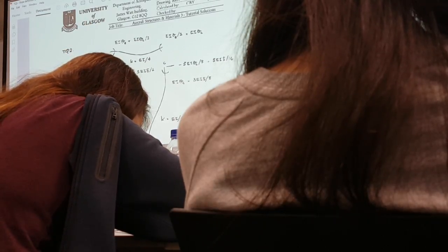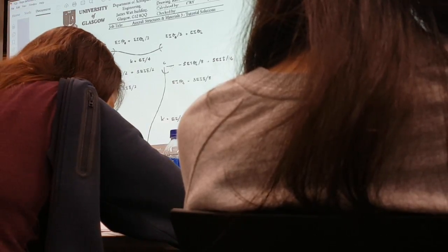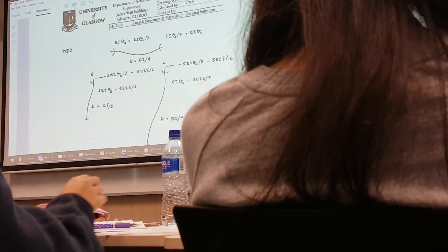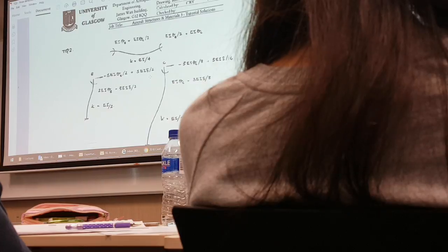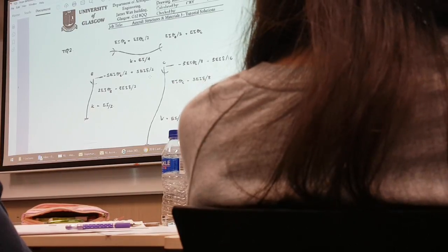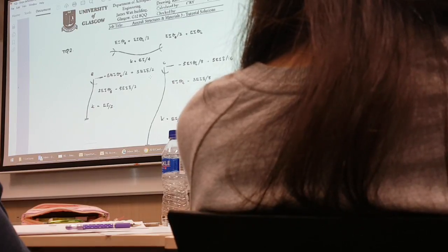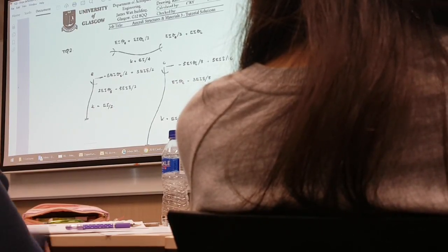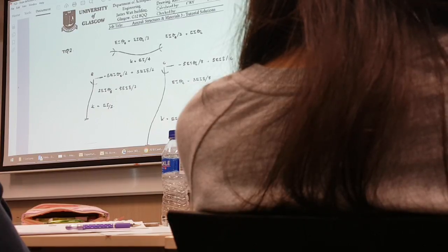Alright, but of course, take note of what the convention is. The convention for this is C and D. By right, if I were to flip the member to be node 1 and node 2, where is the force supposed to point? It is supposed to point from right to left, so from right to left is positive. But now your force is pointing from left to right. So you really have to take care of the sign, because by taking the convention of the sign, you will then be able to get this particular expression.